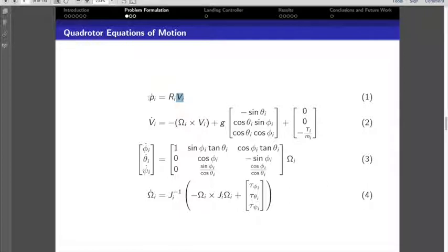Okay, so then you can work on the reduced state. Maybe you want to include that slide that says that the states that we will work with will be the position pi dot and the psi i dot. Okay, so 4 equations. These are 3 equations. It's a 3-dimensional vector, and then the 4th equation is the psi i dot. So total 4 equations is what you will be using. So total 4 states. Reduced state is basically 4 states: north, east, down, and your turn rate. Okay, and your input is the body frame velocity vi, and which can be seen in this figure.